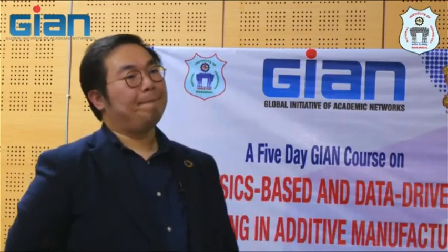When you are discussing a multi-scale model, as we all know, to have a very tiny melt pool we need something like a laser spot diameter of 80 micron or so. But you go to atomic modeling, where you have shown a picture of molecular dynamics. That's a representative. So how feasible is that, even though the melt pool size is around 100 or 200 micron? How can that larger scale be converted into atomic modeling to simulate the process?